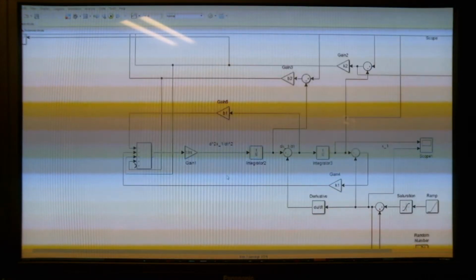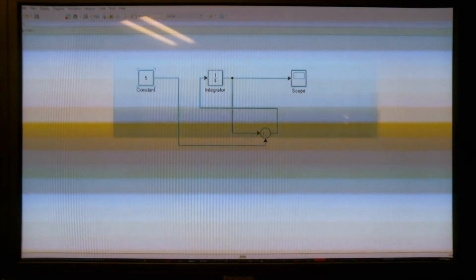So the way that you can create a simple F equals MA simulation, which is what this is effectively, is, you want a sum block, and instead of just two components, you want to have as many forces as you expect to have on that component. So in this case, we have our damping force, our spring force, and that's it.